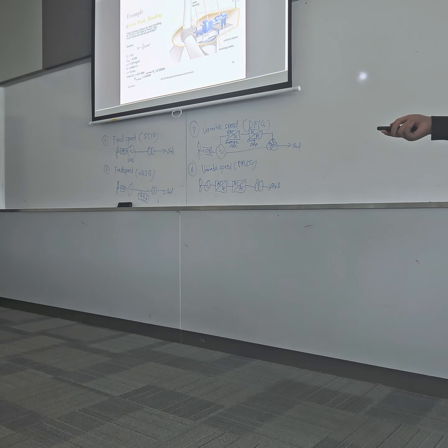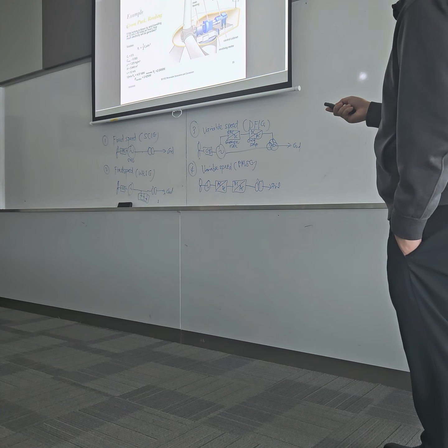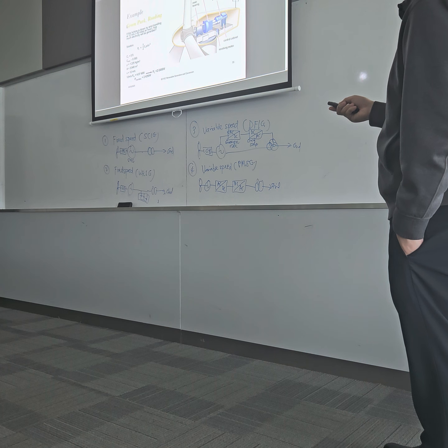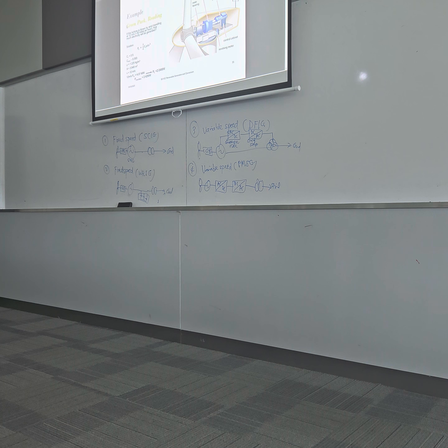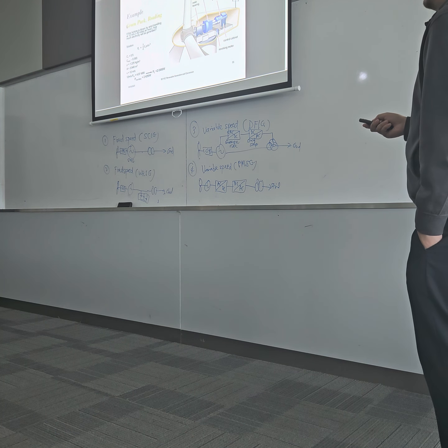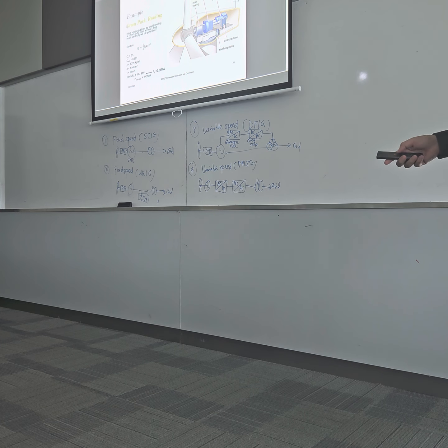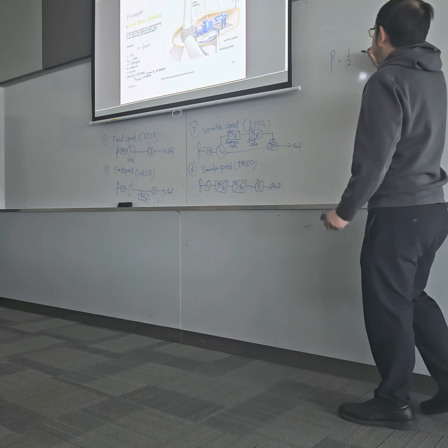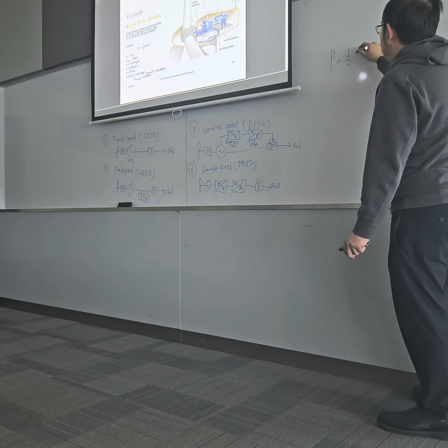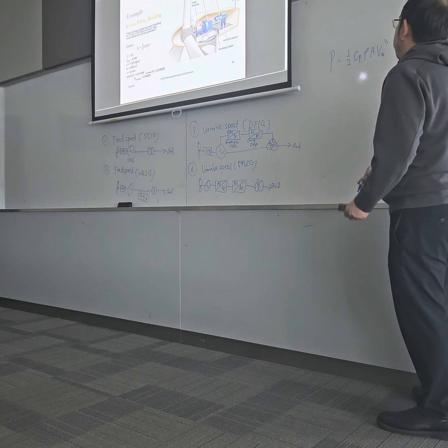So let's do some calculation here. If this turbine is blown by wind traveling at 12 meters per second, how much electricity will be generated? From the simple equation that we have learned, power equals half Cp rho A V cubed.